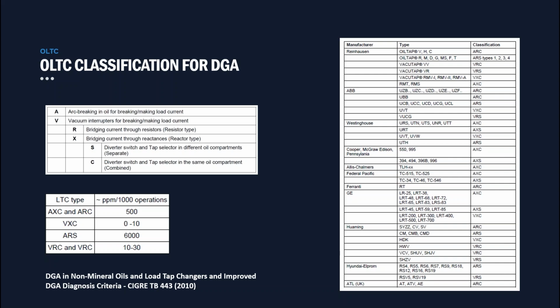You should still do oil testing on transformers that are offline, but the focus is on the moisture levels, and we'd also look at the dissolved gas analysis for changes in the oxygen levels in the oil. For instance, if the asset is hermetically sealed, any changes in the oxygen levels could indicate problems with gaskets and oxygen getting into the transformer. And regardless of whether the transformer's online or not, we need to keep oxygen levels low and also the moisture levels low.